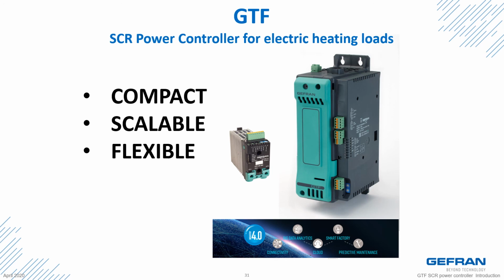The GTF power controller is flexible. It has multiple operating or firing modes and multiple feedback and control output configurations to meet the various heating element control requirements. It has the capability to be controlled by an analog signal, a pulse width modulation signal, or by an automation controller using a Modbus RTU digital communication interface.